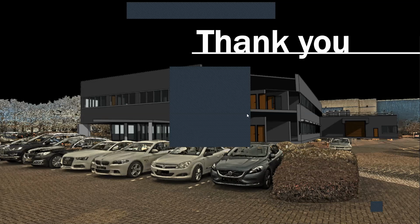Okay, so there are two things. One thing is, if you are doing this 10-kilometer pipeline survey with a terrestrial laser scanner, it is possible depending on how you have done it. There are various ways with scanners where you can go with targets, or you can even go with GPS-based analysis. But yes, a mobile mapping solution can run at 50, 60 or 70 kilometers per hour and can capture this.